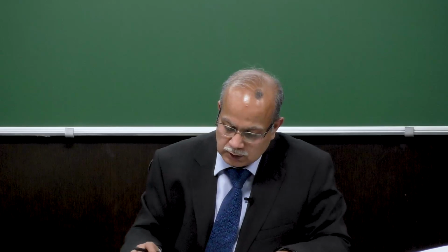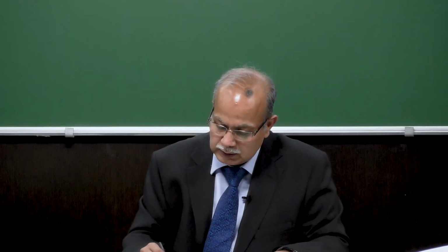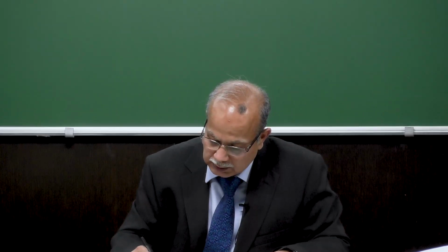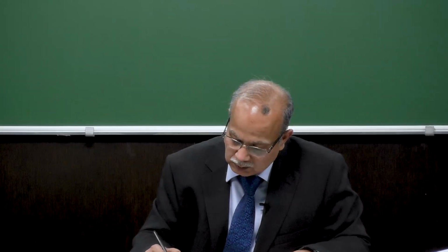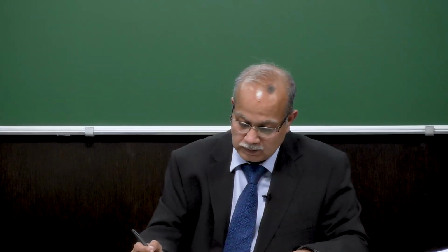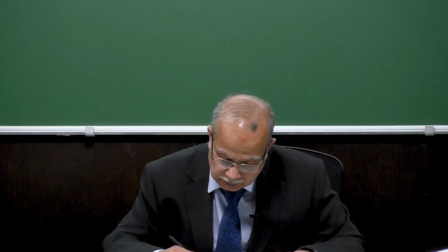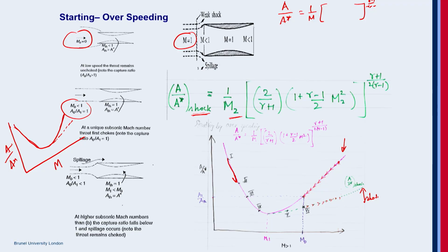This is the expression for the shock solution. Here you can see this one is isentropic and this one is the shock solution. Once you start from here and travel all the way here, with the formation of the shock, you end up in the shock solution. Now you try to overspeed it, basically increasing the flight speed, and come to a point here.